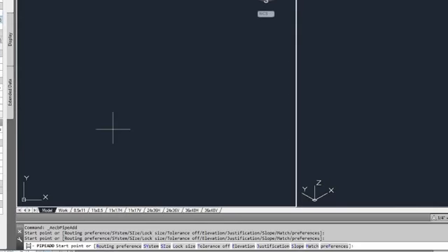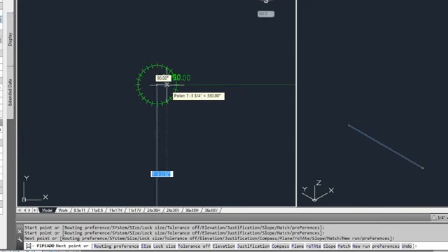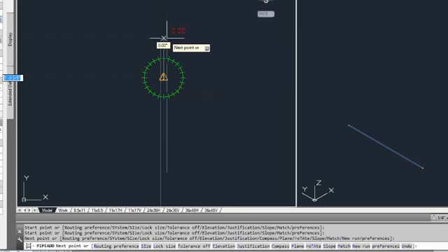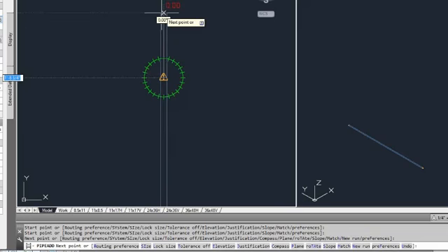So I'm just routing a single piece of pipe, and I need to offset up and over something. There's a couple different things I can do. I know that I'm routing at 10 foot. I have my bottom of center here, so I know the bottom of my pipe is at 10 foot. Let's say I just want to do a straight 90 up and over an obstruction, another pipe that's maybe moving